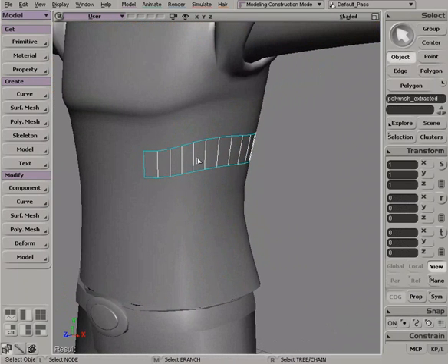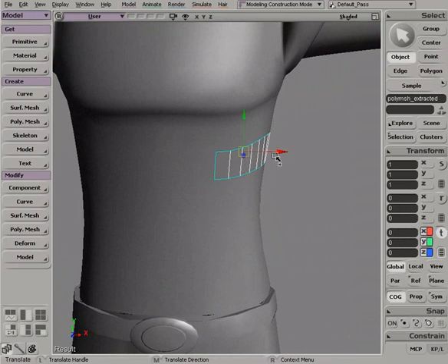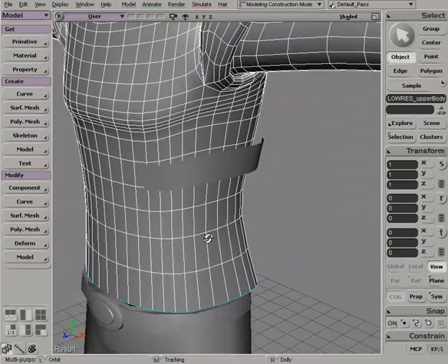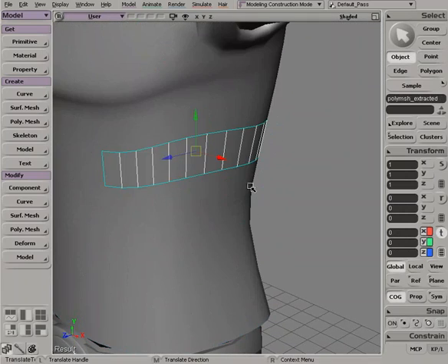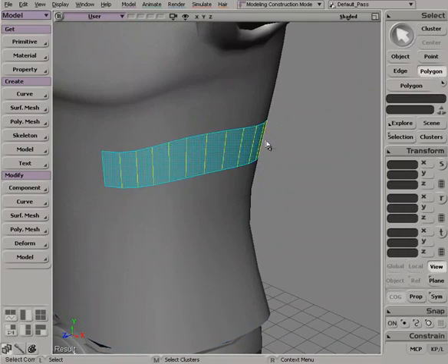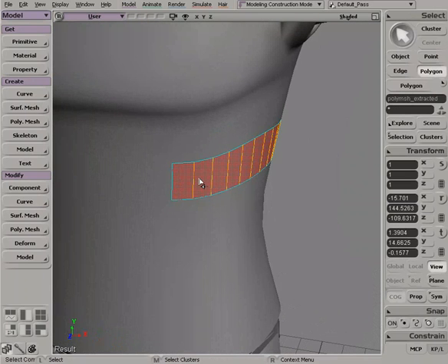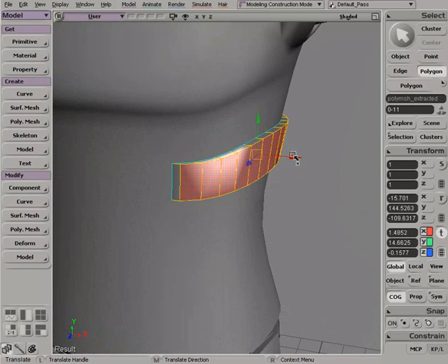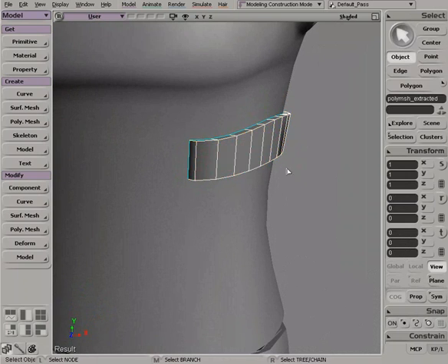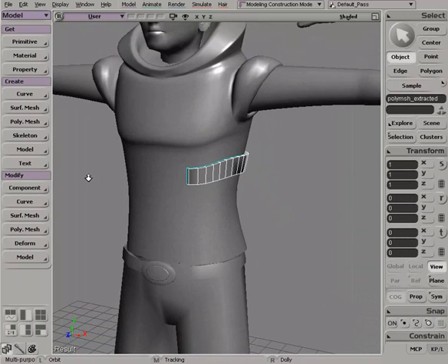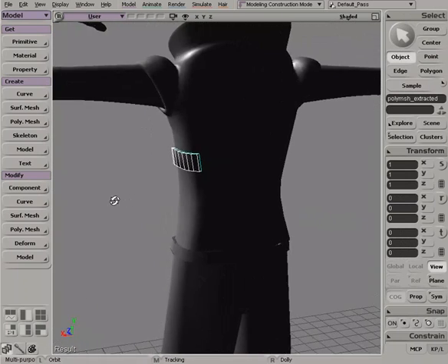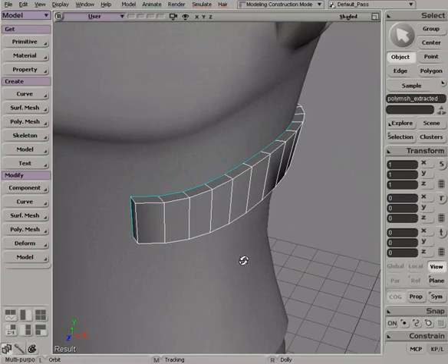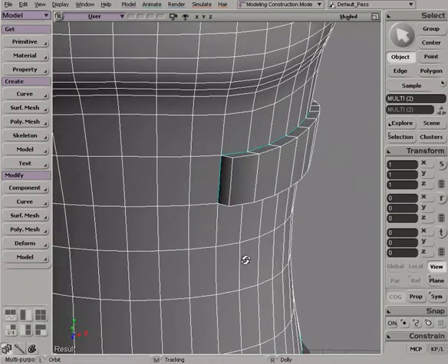And you can see what that does is actually generates a new piece of geometry, basically rips off those faces for me. Right, just like so. So now what I can do is switch back to my polygon selection, select all of these polygons, and just simply Control D to duplicate these faces. Maybe scale this up just a little bit. Right, and you can see now we have this nice piece of geometry that conforms perfectly to this chess piece.